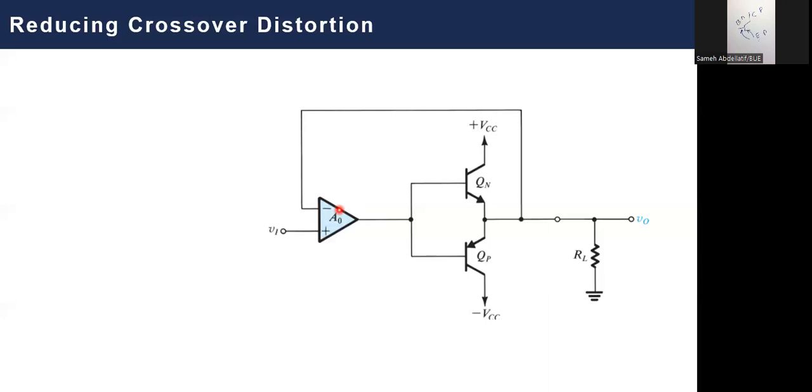However, we have to be honest that it's not simple like that, because this is still a very complicated schematic of transistors. This differential amplifier, this simple triangle, is not a simple triangle. In reality, it's a schematic of transistors. So you increase the complexity of the circuit from one hand. And another important point is that you also lose some sort of efficiency, because this will work with VCC and negative VCC, and there is some sort of power dissipation here.